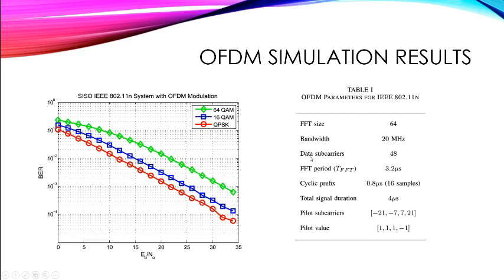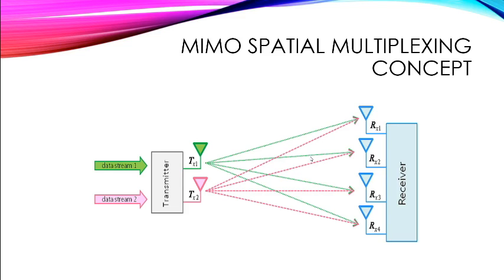Usually in a system, as I showed at first, OFDM and MIMO will be combined. But for the purpose of simplicity, I just simulate them separately. So I can use the channel in the frequency domain to work with MIMO equalization. Otherwise, it is very difficult. It is possible, but it takes more time.